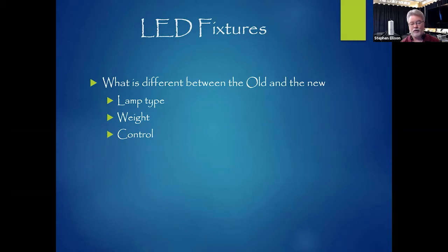And interestingly enough, I was wondering for years, how are they going to get around that? Because the ellipsoidal reflector spotlight that I grew up with required a lamp that produced a single point of light. And then lenses focused that image so that you could project the image. The first thing you thought about when you projected the image was the gate in the lamp, because that was a circle. And then you brought in shutters, and you could have shutter cuts, and you could focus the edge of that shutter cut, and then you could put gobos in, and you could focus the gobos.